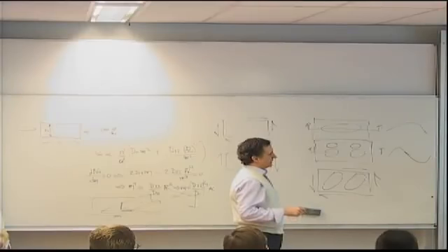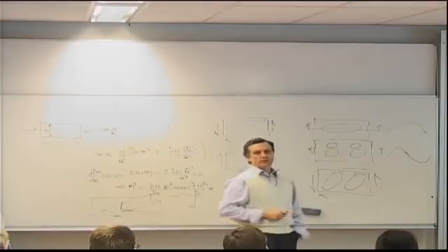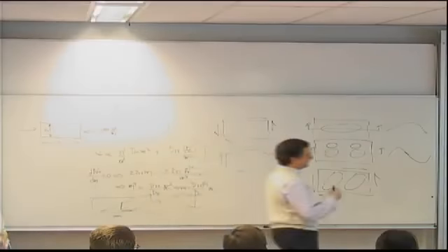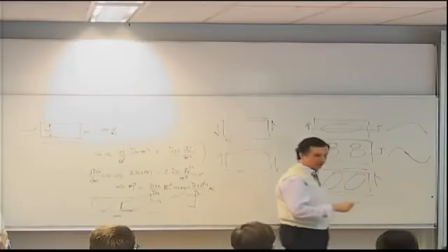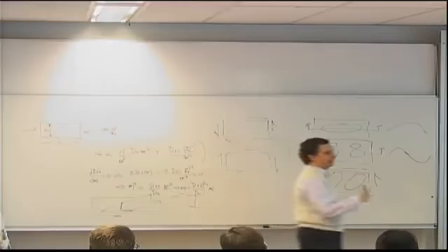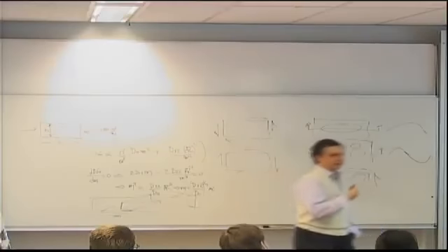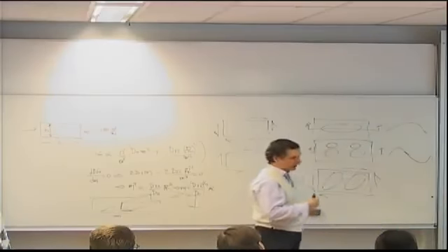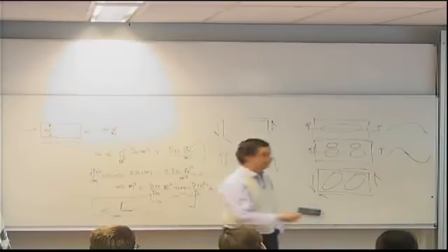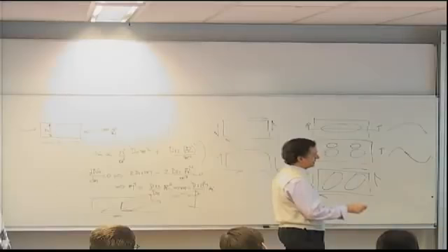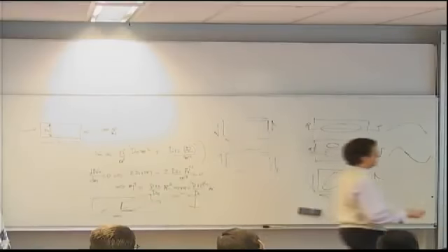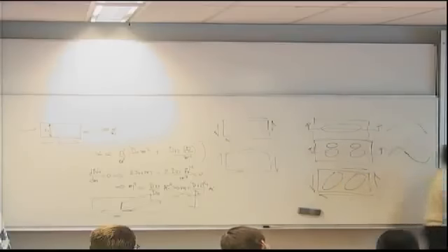But in fact, for what we are about to do, which will involve minimization of energy, I don't need to satisfy that. We are making an assumption on the displacements equivalent to satisfying the strain compatibility, and by minimizing the energy, we will satisfy the equilibrium equations and the force boundary conditions approximately. It so happens, for this assumption, we actually get this satisfied, which makes the solution a little more accurate, but this second set of conditions is not necessary to be satisfied.